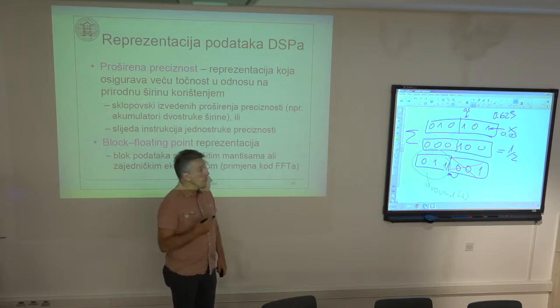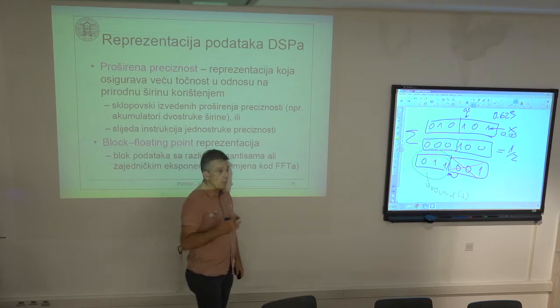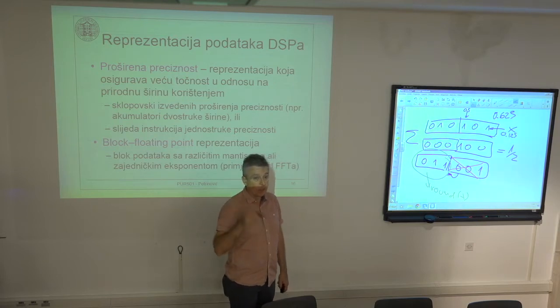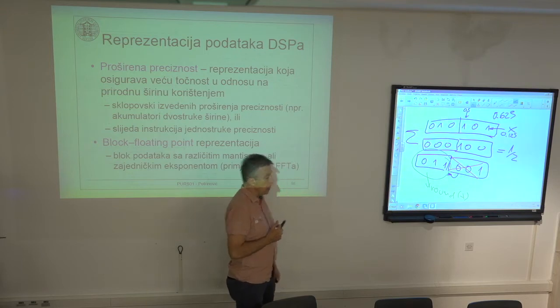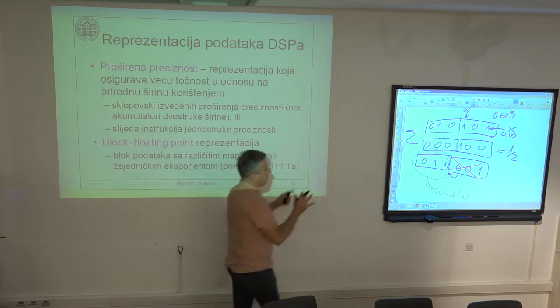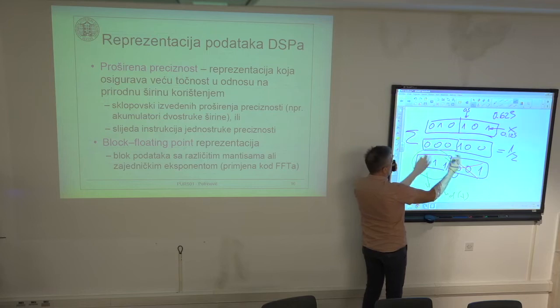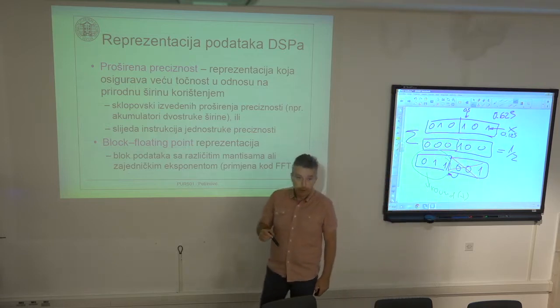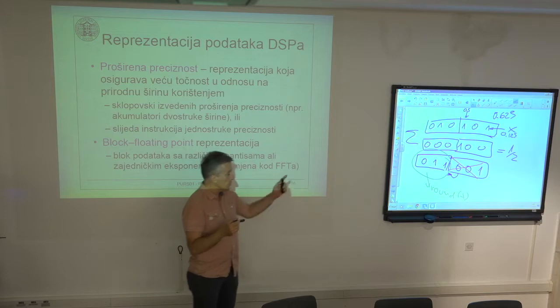This rounding is performed in hardware as a part of the multiply instruction. We will later show that we can invoke multiplication, but with rounding. After computing the double width product, the 1/2 is automatically added to the lower word after shifting to the left, of course.